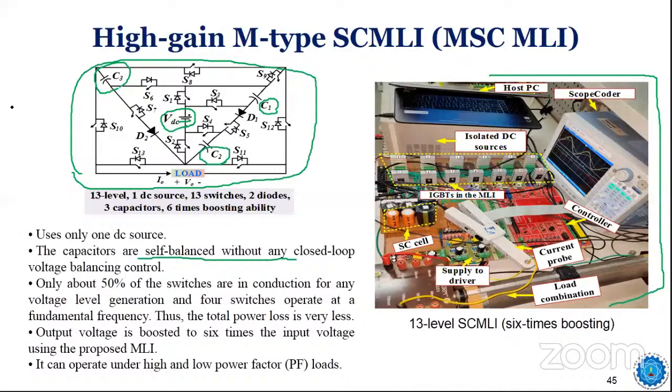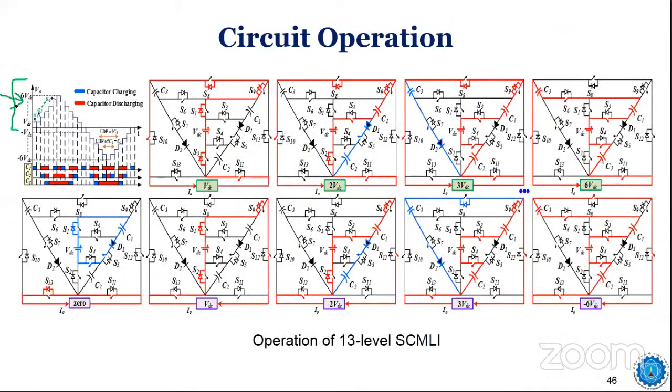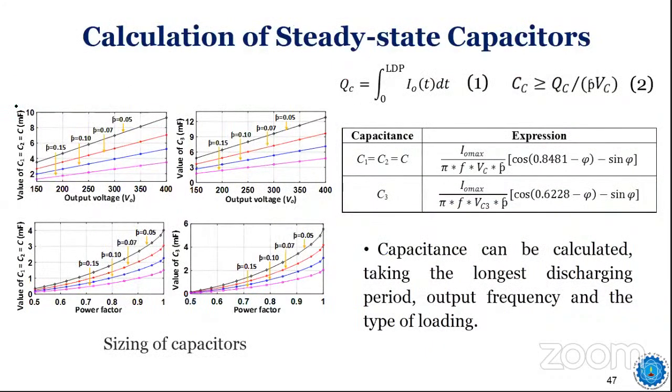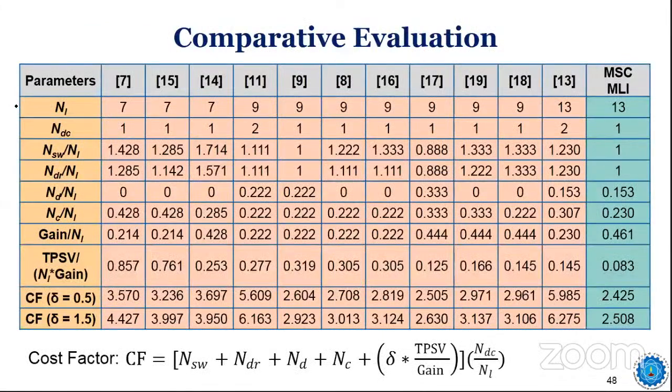Do you still need a boost converter? Just think about it. Do you still need a boost converter to boost the voltage? No, because I'm anyway boosting the voltage to 6 times from one single input. So for this working operation, you need to follow some of the papers I will show you at the end. The design aspects, the comparison, how to get the required output, all this is clearly analyzed here.